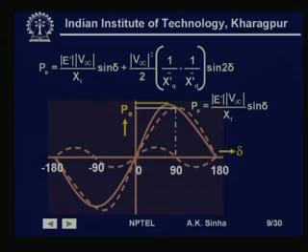So this is how we understand the steady state stability of the system, that is with very gradual changes. We call this kind of stability, that is the maximum allowable power from a machine to the system, the steady state stability limit. Beyond that point, the stability of the system, even under steady state operating condition, is lost.